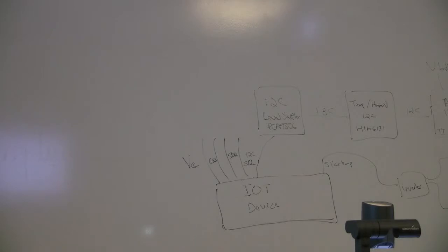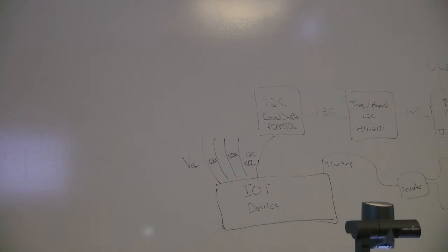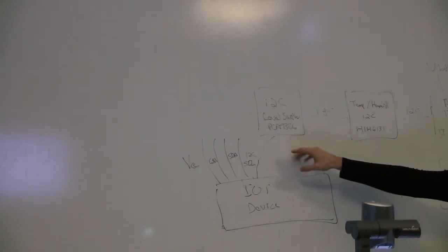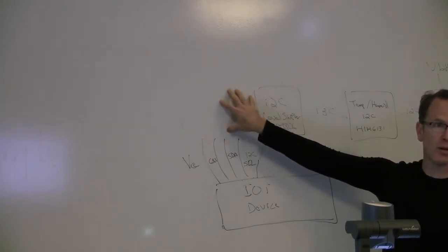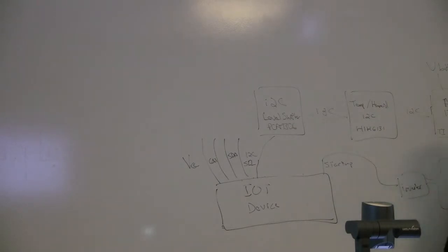Yeah, and one of the reasons I did is the LinkIt ONE specifically said my digital I/O is all 3.3 volt. Don't give me 5; it'll hurt me. So that was one of the reasons, the motivation for that. And now that I've done it, I'm like, why not? You know, it's relatively cheap. It only has, you know, this part, 2 resistors on this side, and a couple pull-up resistors on this side, and that's it. So it's a pretty painless thing to add.